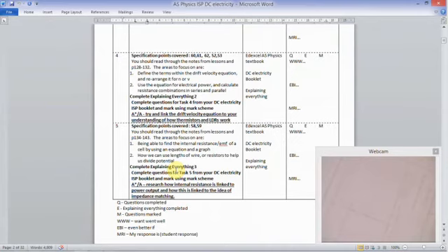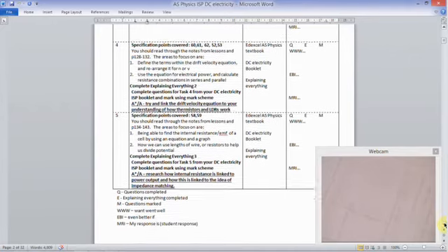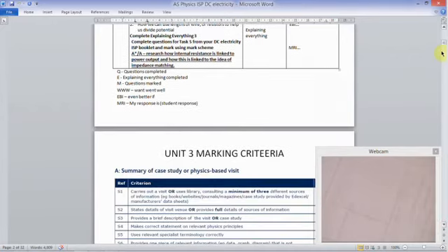In terms of the A* style concept, it is not part of the spec. It's to do with the idea of impedance matching and how internal resistance is used in that. It's used in acoustic engineering actually. In that situation the load resistance of a circuit is matched to the internal resistance. And if you match those two things perfectly, you get maximum power being released. So that's the Max Power Theorem, clearly named after Homer Simpson. If you don't get that reference, you should be watching more episodes of The Simpsons.